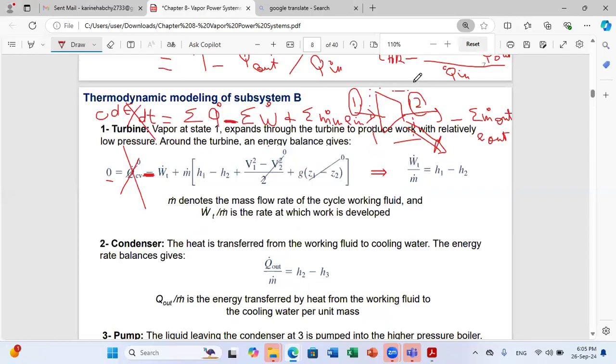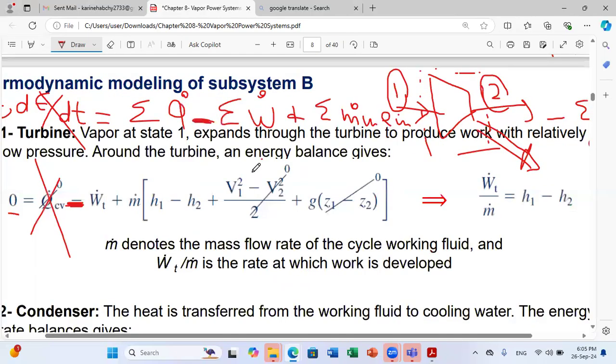We have learned that whenever we have an open system, the energy of a fluid is decomposed into the enthalpy H1. Always when you have an open system, you need to account for the work of the pressure forces, and with the internal energy it is lumped in the enthalpy.